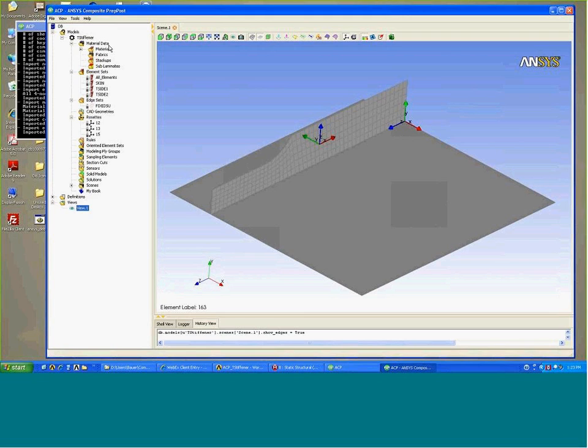We'll set up fabrics, such as materials and thicknesses, and we can also collect stackups and sublaminates, which allows for essentially a hierarchical list of organizing our materials, creating collections of materials to then go to our model and apply in the distinct zones or regions. So that's our material data.